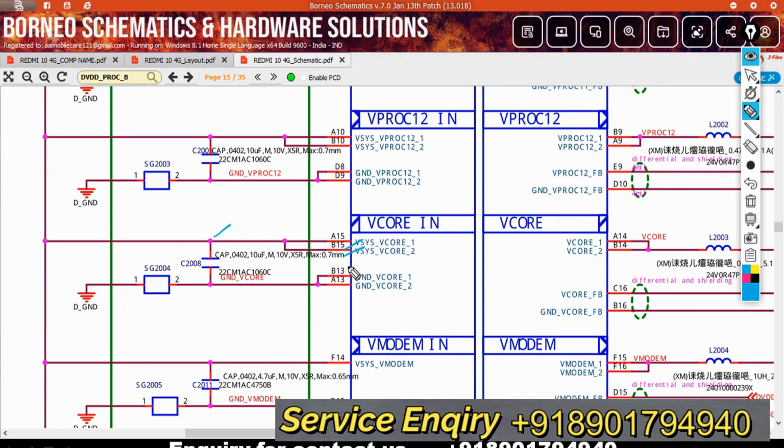If your phone had water logging, let's say, these lines internally may be burnt or damaged. When you measure, you will get 3.7 volts here, but internally these pins are not attached properly, so your output is in a fluctuating mode.